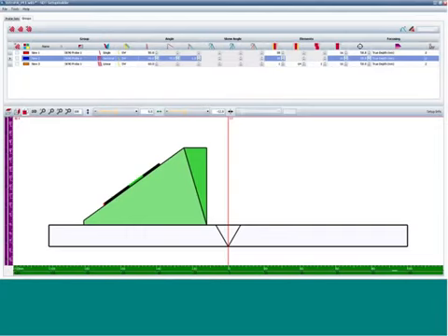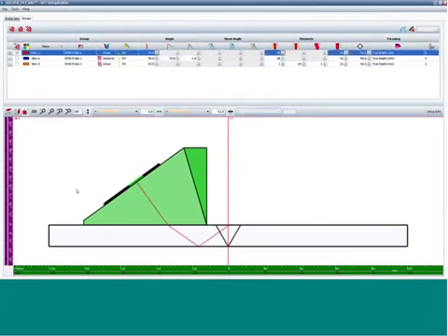So if we were to look at a single group that includes one static A-scan here, to put in play some of the terminology that we talked about, the single A-scan here is being developed from our phased array probe 1. We are asking for a shear wave velocity refracted angle in the material of 55 degrees. I can change that angle directly in the calculator.